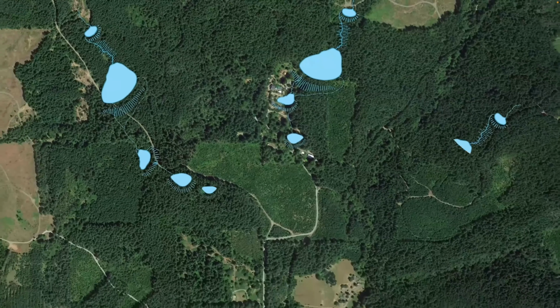Now, if in your excavation you dig down and you hit fractured bedrock or some more porous layer at the bottom of the pond, a workaround for that is to lay down a blanket of clay that sits atop that layer, which ultimately would be the impermeable bottom of the pond. And it's very important to key this into the dam so that there's a complete seal along the entirety of the bottom of the pond.